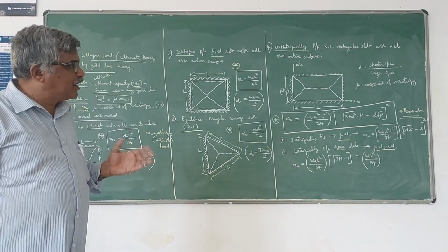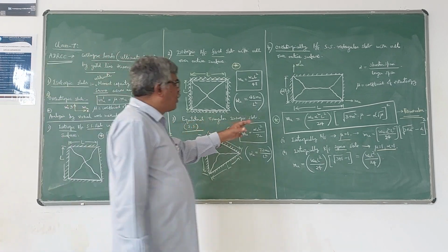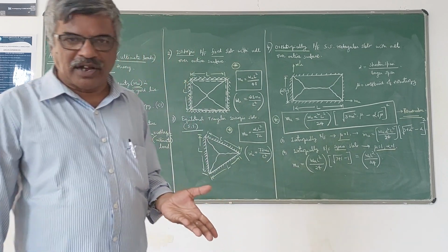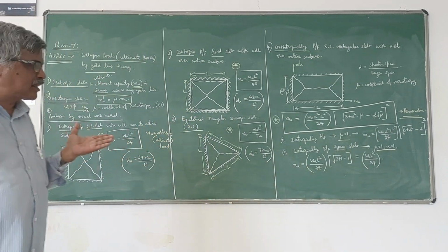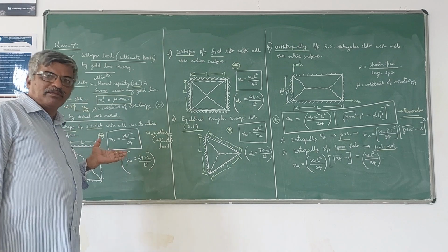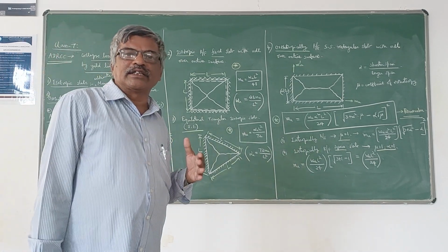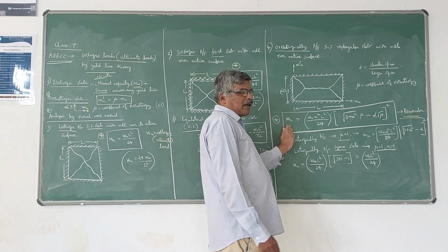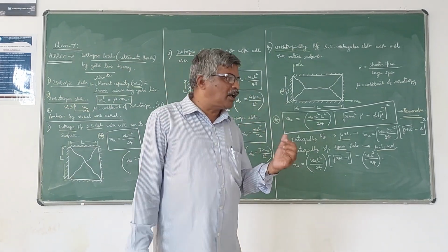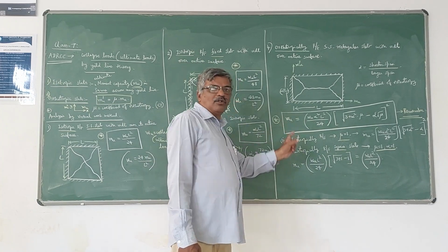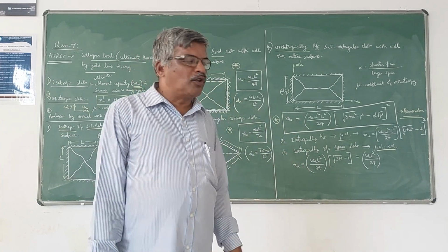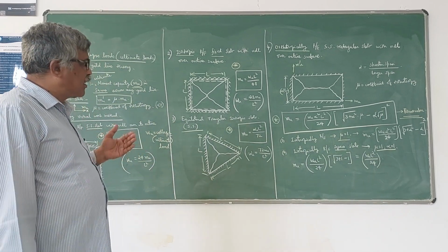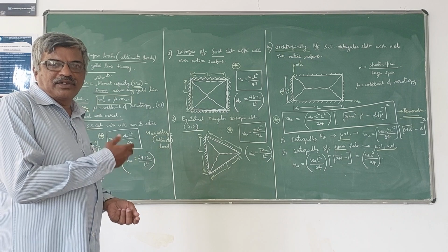That's all. So the small mu is nothing but your capital Mu, which we are using in the RCC design. So in the last lecture I explained about the design of continuous beam. There capital Mu is nothing but the maximum bending moment. Here this is nothing but the ultimate moment capacity. So we are going to take this small value of mu for finding the reinforcement that is required for that particular slab. So in the next lecture I will be explaining one design on this yield line here.